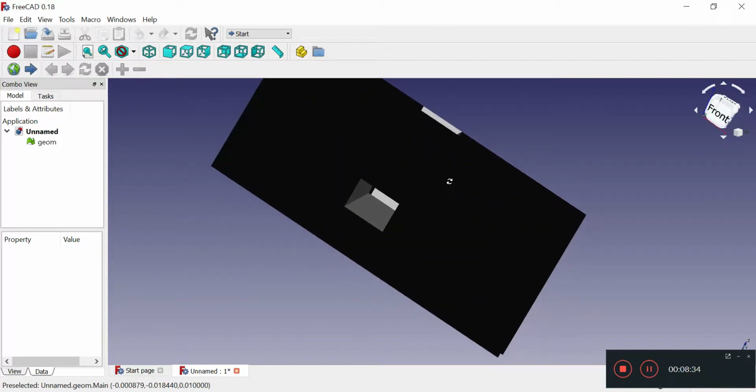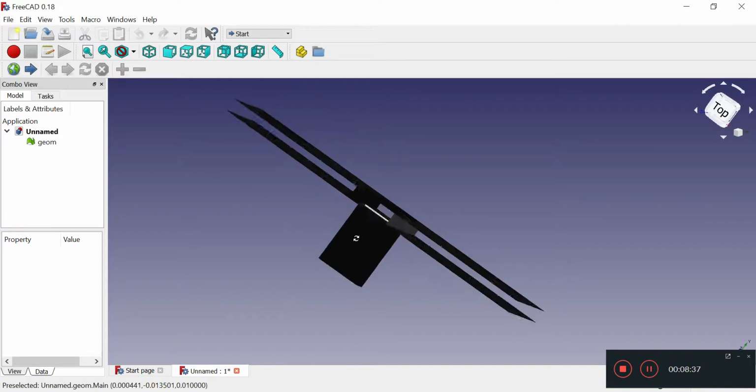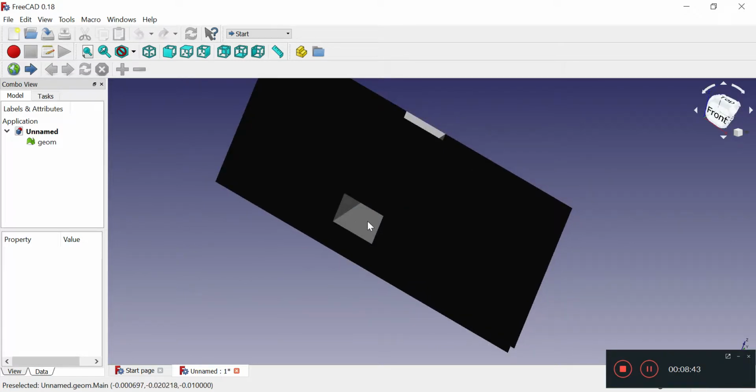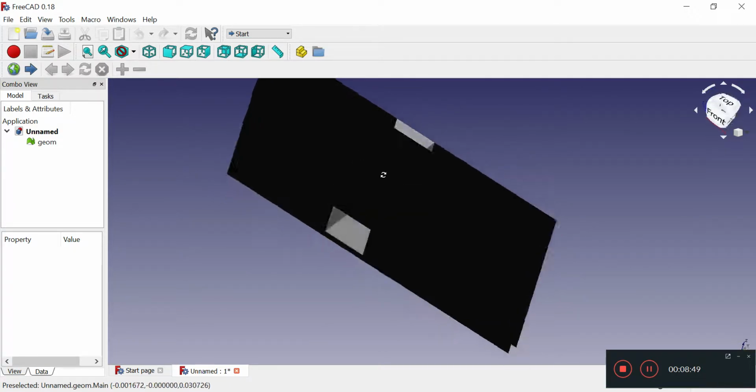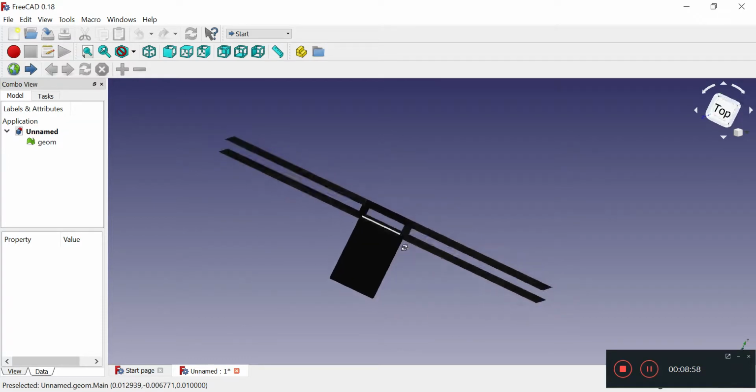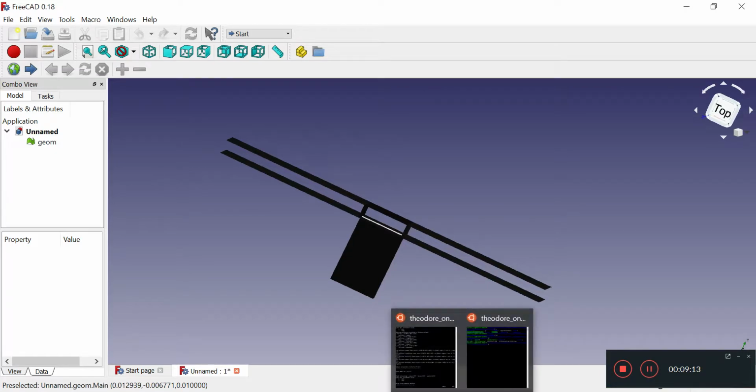So if you want to define a region, you have to ensure the region itself is enclosed. It's not like we have some random piece of item lodged in here, like a sphere that we want to lodge in here. I think there should be some different way of defining that. But that's how this case is structured. So we can use snappyHexMesh to do this kind of thing where we define regions. So that's not a problem. The only thing is that for more complicated geometries, we will have some other considerations.